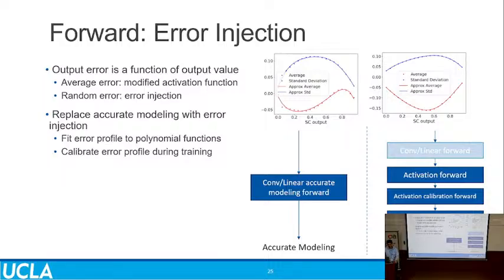I don't know of a single commercial system which uses SNNs, and there's a reason for that. At least our feeling was that if we develop custom hardware, it has to be able to run standard models. There have been approaches developed in recent years which try to map conventional models to SNNs, but then it starts to give up the main benefit that SNNs have, that asynchronous nature of operation.